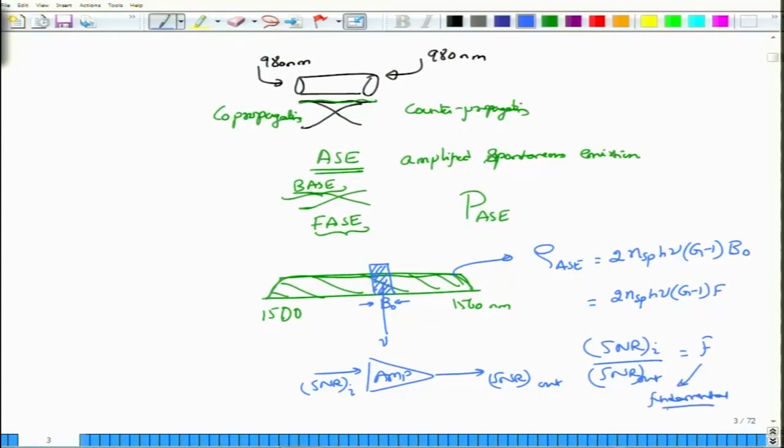Okay, it is something that cannot be just wished away, saying that I can throw this out. It is not possible to do so. So this noise figure is something that comes fundamentally from the physics point of view, and therefore cannot be thrown out. Now this was actually the power spectral density. Power spectral density will be measured in so and so watts per hertz. When you multiply the power spectral density with the bandwidth, you will get the total power.